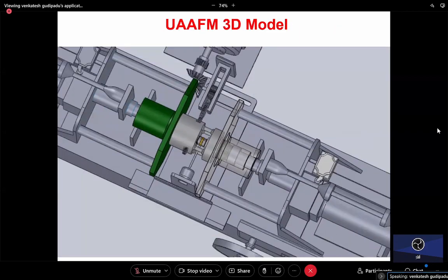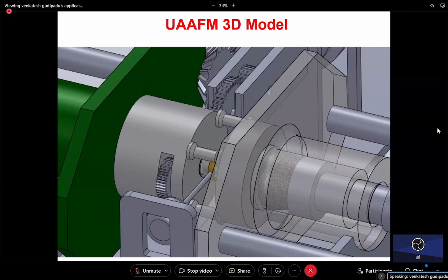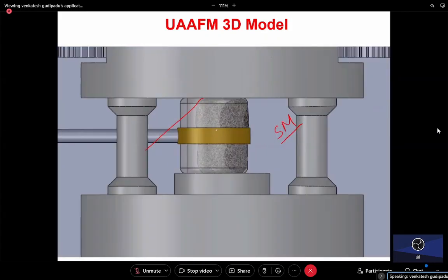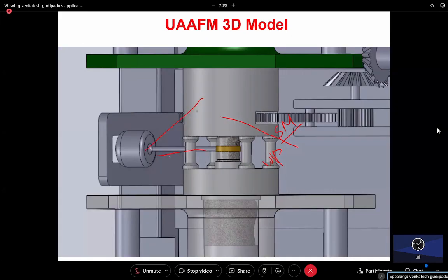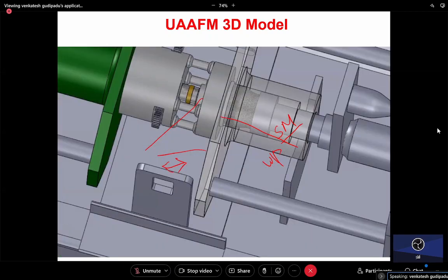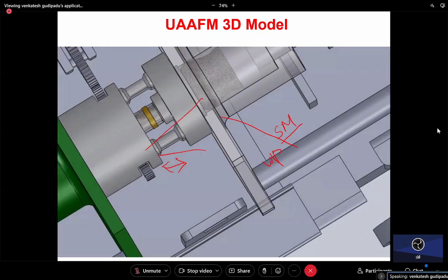Just an idea you can see. So we are pumping the medium. So this is the semi-solid medium, and this is my workpiece here. So this cylindrical bush is the workpiece. Yeah, and here you can see we are vibrating the workpiece by using the attachment. Why we are vibrating is for getting an additional advantage. And what is my target? To finish the internal geometry of this cylinder, right? So the process is new here.